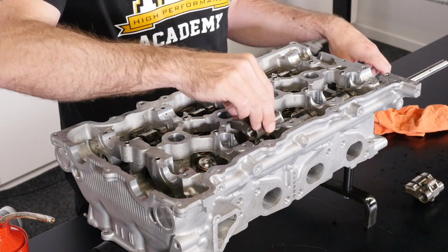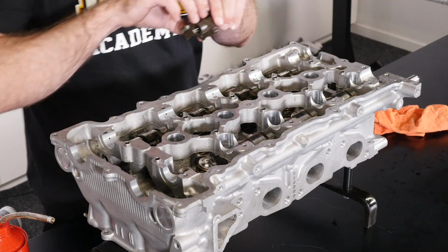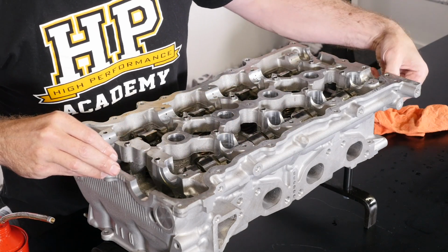So you need to be very mindful, and there's often some pretty extreme changes we make in the cylinder head to cope with an ignition cut limiter and making sure that the engine is going to remain reliable. So if in doubt, stay away from an ignition cut. Use a fuel cut. It's much safer on all engine types. However, fuel cut will not work as well for this strategy.